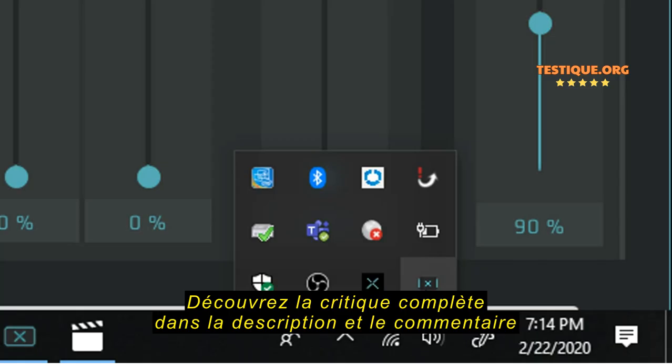The other thing that I found is that sometimes when I start up the GoXLR hardware and I have the mute button on, the channel's not muted, and there's no way to really tell unless you have a headset on and you're monitoring through the headset out jack on the hardware interface itself. The levels on that compared to the levels that you're recording at are nowhere near the same, and you're not hearing what you're recording. You're hearing what is going into the interface directly from your mic, and then after the interface is done with the EQ and compression, it sends it over the USB to your PC, and that's where things get muffled.